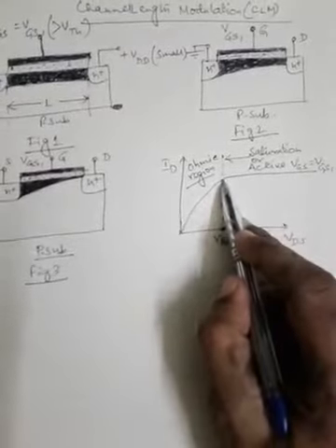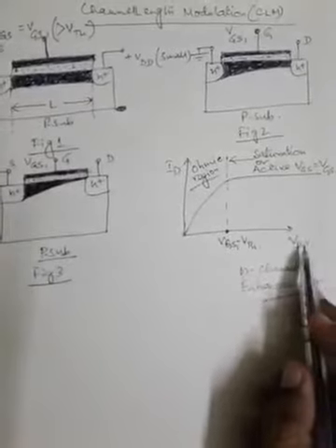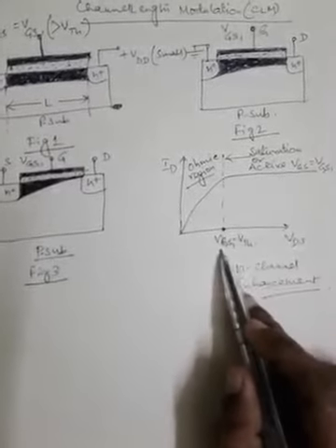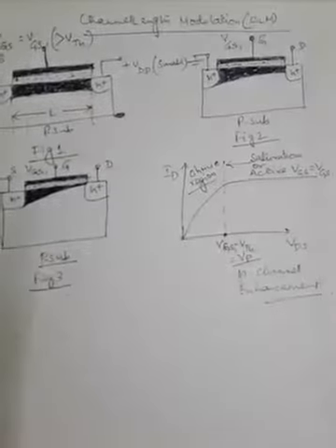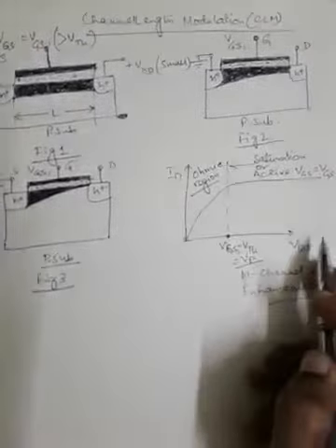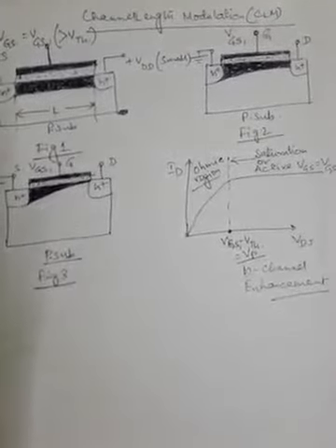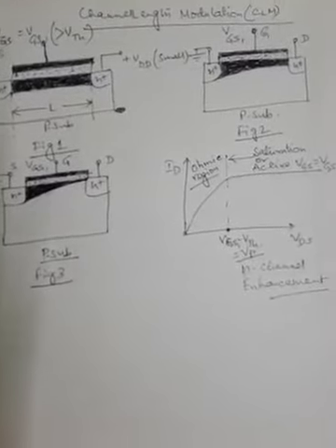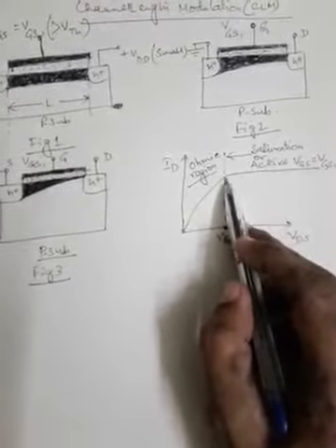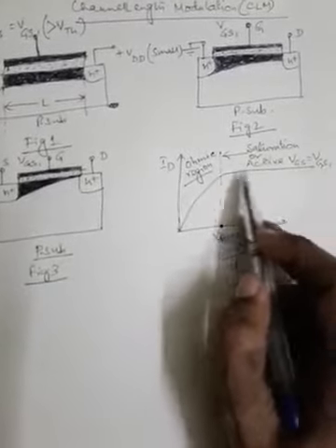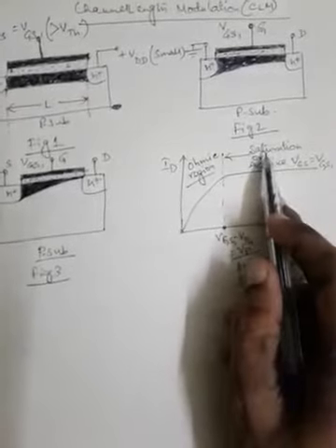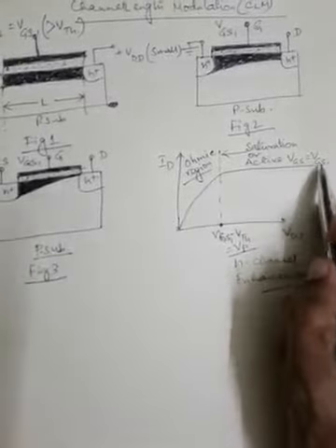After this voltage is applied between drain and source, which is called the pinch off voltage, here written as VGS1 minus VTH, this is nothing but the pinch off voltage VP you have seen. Once this pinch off voltage is attained between drain and source, the current becomes constant and thereafter no longer increases. That region of operation is generally called the saturation region, or sometimes the active region, and during that operation VGS is equal to VGS1, the applied value. So these are the VI characteristics.